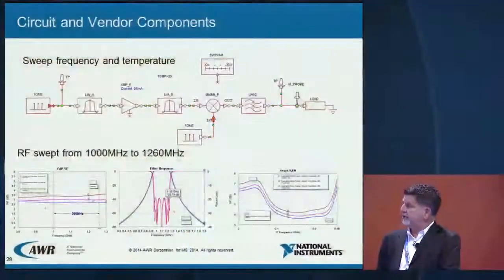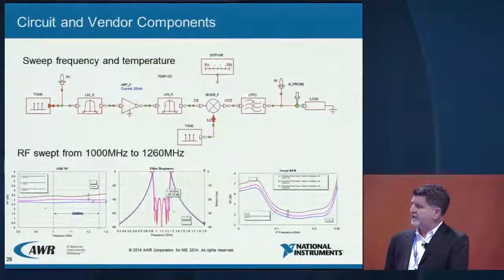So the steps were ideal, circuit-based model, commercial off-the-shelf component, getting closer to reality in our design. The next step is that we can do an analysis. Here we're doing frequency versus noise figure over temperature. A specific bandwidth has been defined. Each color indicates a different temperature, showing the characteristics of the filter that we're using.